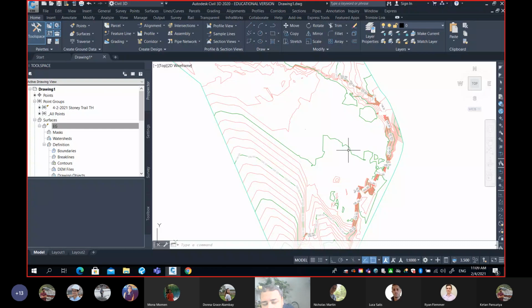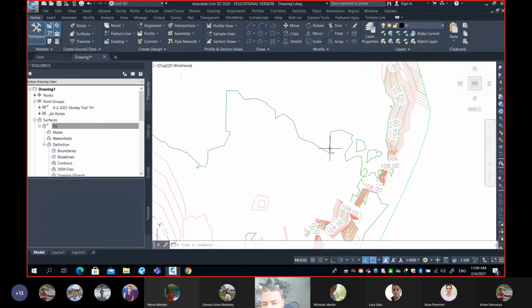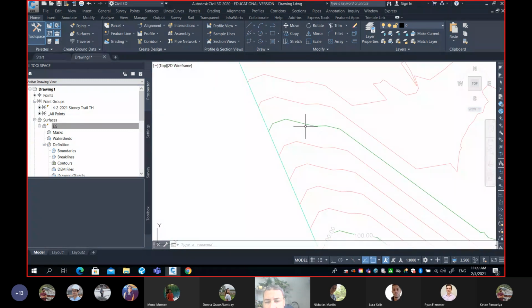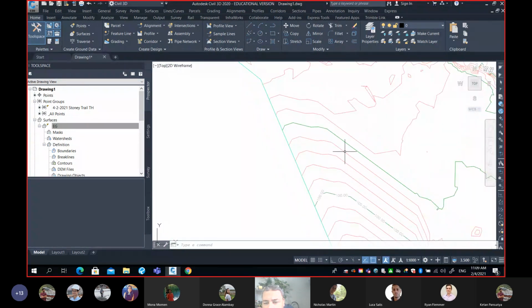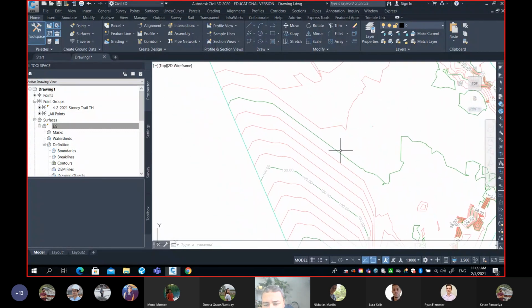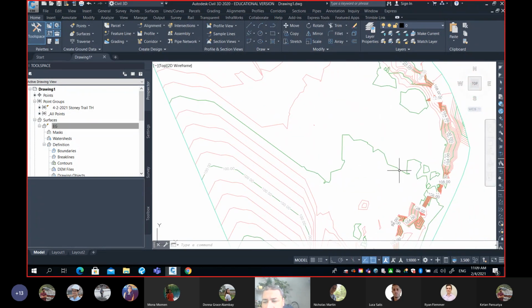Anyway, so guys, you need to understand when we create contour maps, one label along a very long contour line is not okay, because think about it this way. I'm a designer. I'm working on my map and there is a 100 here while I'm working on this area. Visually, I need to follow my contour line until I see the 100 to know that the elevation is 100. However, if you label your contour line reasonably, like one label here, one label here, and one label there, then it will be more usable for the map user or designer. So for a long contour line, we typically add more than one label.